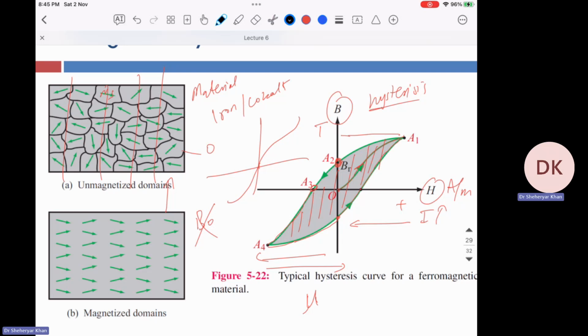Different choices of material can produce small hysteresis, and some materials can be here, but this can be very flat. There are different choices of soft materials and hard materials, and it's up to you to decide. So when we have motors and transformers, we have losses. Heat losses, which are I squared R losses due to resistance. And then we have hysteresis losses, due to the iron being used inside the motor or transformer. So this is a very interesting property, very different from the E fields.